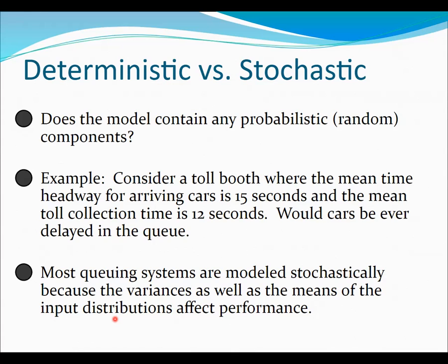So you'll run the same model maybe 5 times or 10 times, and then you average those runs. How many times you do it depends on a lot of factors that we'll get into later on. But why do we use multiple seed numbers when we are running simulation models? It's because we're trying to account for that stochasticity.